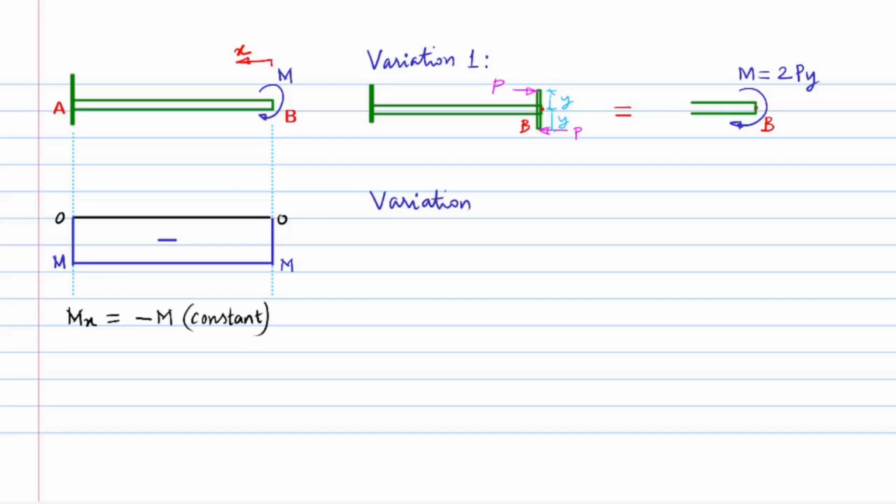Likewise, suppose we have a right angle frame of height A and width B as an extension to the beam, say at the free end B, over which we show a downward point load P at the end of the extension as indicated here. We try to have an equivalent load system acting at B without the extension frame for ease of analysis. For this, we show two loads of value P each in upward and downward direction at free end B along with the load P acting on the frame.